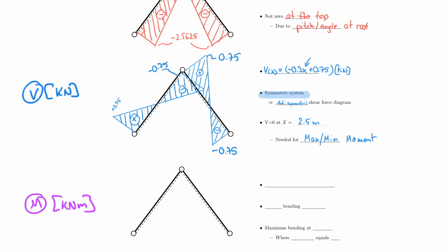Before I do that, I just want to show you that I bring these center points down effectively. But it's important to understand that now I have a perpendicular line which really defines where things are happening. So this would be perpendicular to the rafter itself. And now I can use my basic knowledge about moment diagrams to help me draw this effectively. The very first thing I know is that at each hinge or at the supports, I must have a moment that passes through 0.